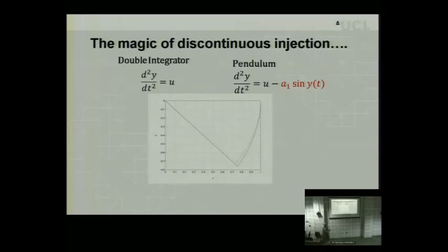And we saw very nicely, this summarizes several of the slides from yesterday, where we had the double integrator. We have the pendulum system, which is effectively a double integrator with some uncertainty. And we saw after an initial transient time, both these systems exhibiting the same dynamics. They both exhibit a first order dynamic response, which is chosen from the slope of this line, entirely prescribed by the designer.